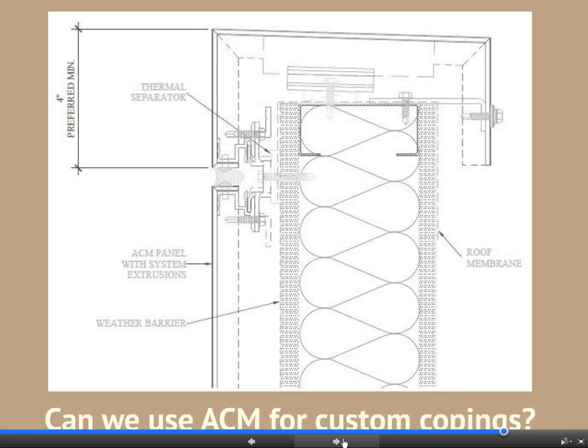He says, "I prefer detailing roof edge securement independent of the MCM coping. This is primarily so as not to involve two different trades, MCM and roofing, in the installation and the warranty of the roofing system. I prefer having only the roofer responsible for the roof system installation." And that makes a lot of sense. It's a great approach. Basically, you need to tie off the roof membrane independently. Now, that's not to say that we might want to put some other waterproofing membrane over the top of that parapet wall construction, as is shown there with the dashed line, but that's not the securement for the roof membrane as such.